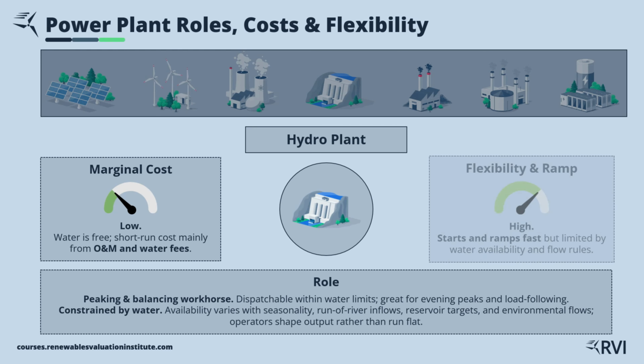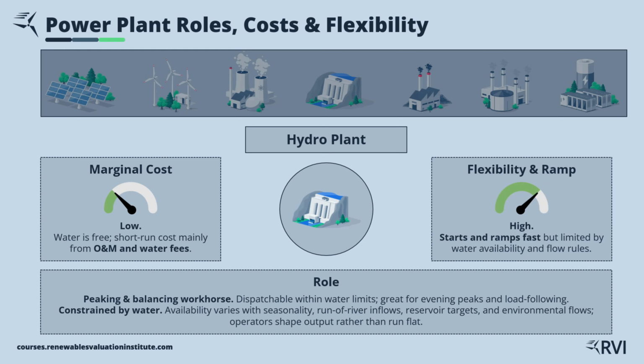Flexibility is high. Hydro can start, stop, and ramp quickly. The catch? It's very energy limited. Output is bounded by hydrology, reserve levels, and minimum flow rules, so operators dispatch it strategically rather than running it flat.